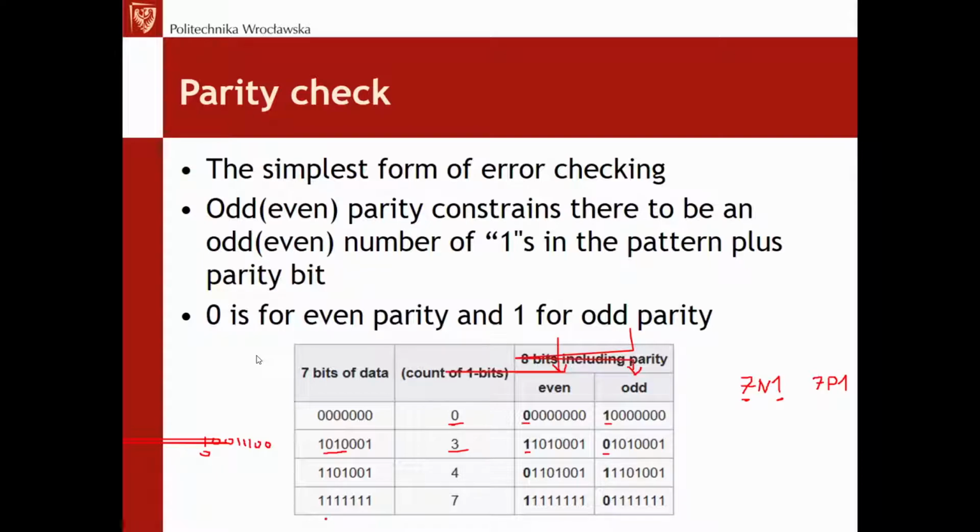This parity checking makes it possible to detect errors. It's only a detection code, no correction is possible, but it will detect 1 bit of error, or an odd number of errors in the number.